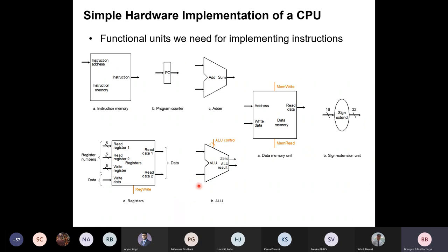These are my basic blocks which you are going to use. And this is my ALU, which you have just designed with 5 operations like addition, subtraction, AND, OR, SLT, branch. And we also need this module. We need to extend the 16-bit address to 32 bits. For example, when you have a branch instruction, or an add immediate instruction, you have an offset value of 16 bits, and then you need to extend it to 32 bits for the addition operation and for further operations.